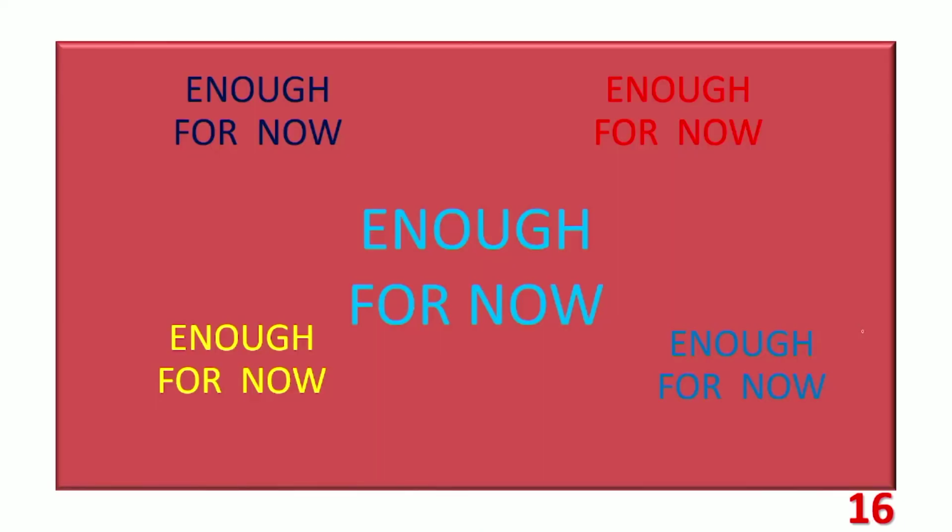With this, we come to an end of the present session. To recap, in this session the focus has been mainly on four types of wire radiators: small dipole, small monopole with linear current distribution, quarter wave monopole with sinusoidal current distribution, and also small loops. We considered their directivities, radiation resistances, effective lengths, effective apertures, beam areas, and some more significant performance indices also.